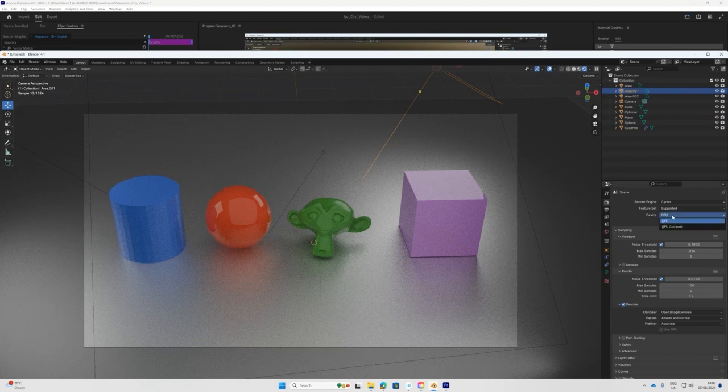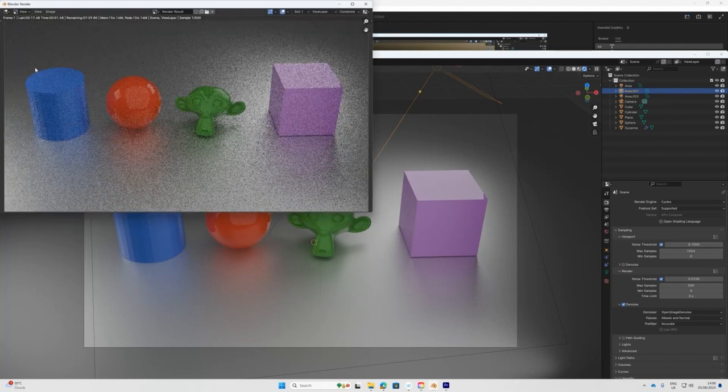Also, in order to render faster, if you're using a PC, if you're using a Mac, you can't. But if you're using a PC, you just use GPU compute rather than the CPU. Okay. And yeah, I'm happy with that. So if I'm happy, I can then increase the samples. I don't know, I'm just going to put 500 for now and then render my image. Save it. Don't forget to save. And I'm going to render. Should take a few minutes depending on...